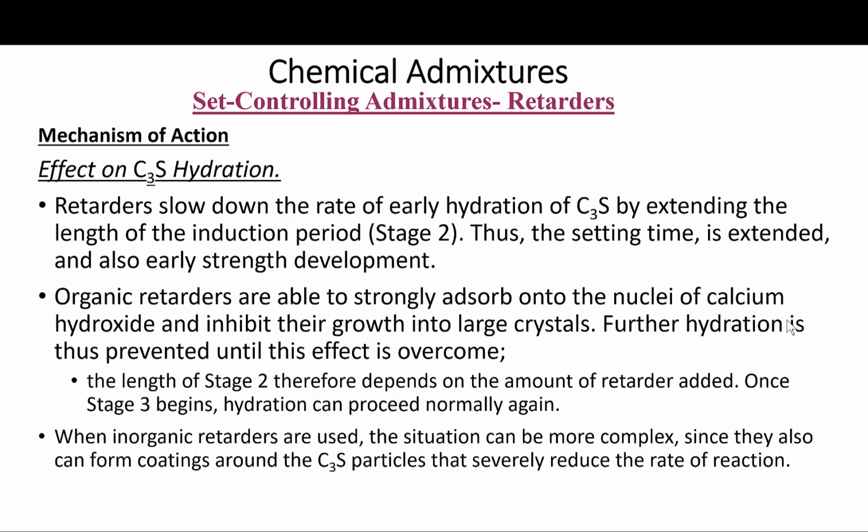can prevent set entirely. For this purpose, deliberate overdosing has helped many ready-mix truck drivers out of a tight spot. A bag of sugar added to the truck can take care of emergencies when excessive delays may cause the concrete to set up in the truck.